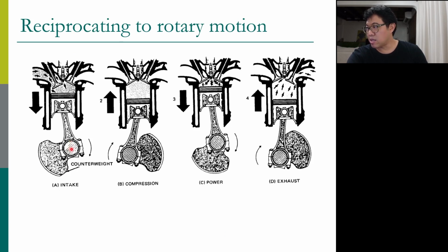The crank center is here, but the shaft center is there. So there's an offset between the crank and the crankshaft. When it rotates, look at it, the crank rotates in a circle like that around the center of the shaft. It moves here, it moves there, it moves there. So it rotates around the center of the crankshaft. That's how we get the rotational motion of the engine.